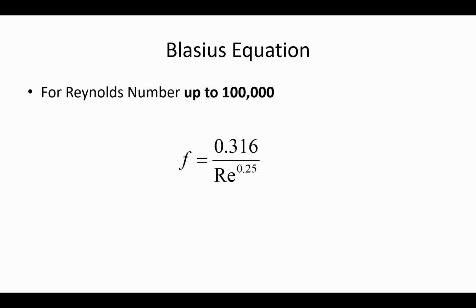It just relies on the Reynolds number itself because we're assuming that the flow, although not laminar, in bulk, the average Reynolds number in the pipe isn't below 2,000, but that cushion, that laminar sublayer that can completely submerge the roughness elements, that layer is thick because of the slow moving flow. So this is another option you have available, Blasius equation, when it's below 100,000.